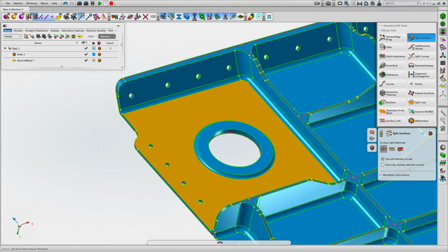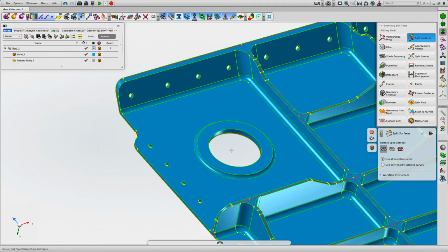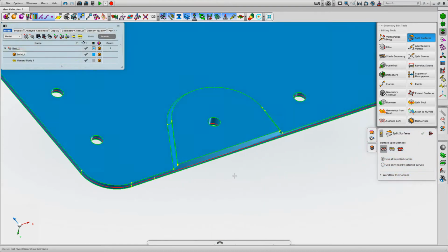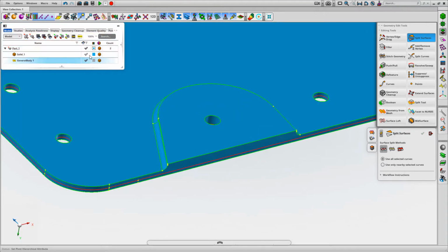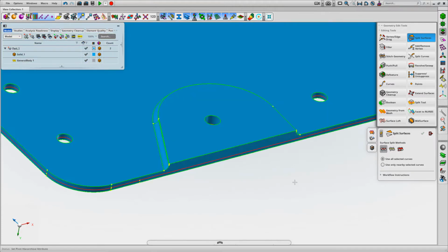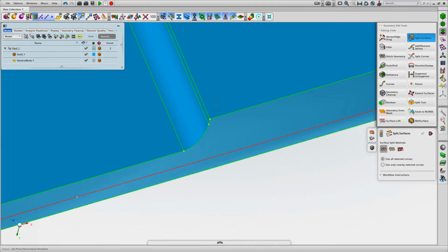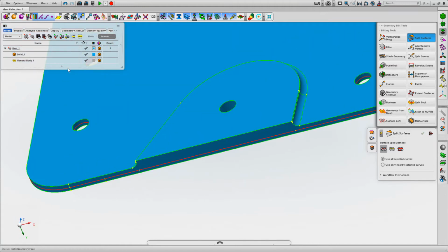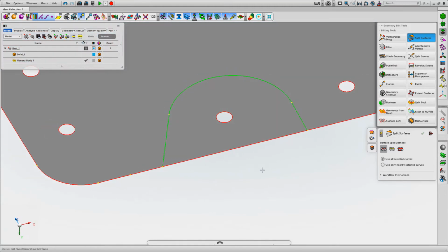I'm not worrying too much about the fillet edge because obviously this is a 2D representation. Same again here. I'm going to have change in thickness, so I need to split the surface. So pick the surface, pick the solid. Again, select contiguous edge, and then we've got that surface split.